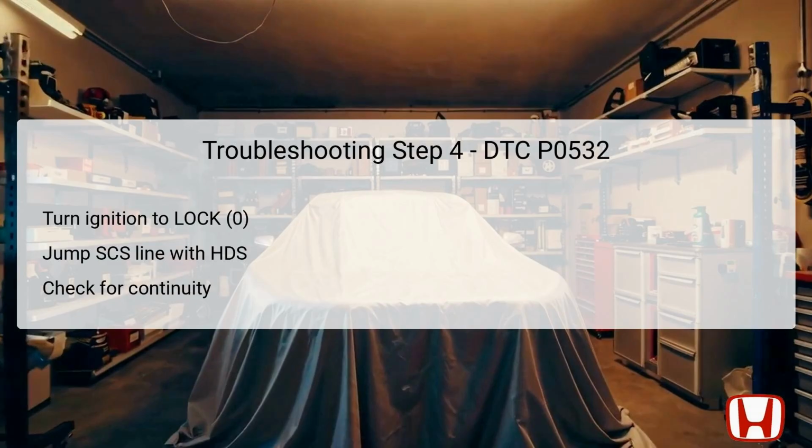Continuity testing is essential to determine if there is a break in the VCC6 wire, which connects the ECM to the AC pressure sensor. Check for continuity between 2 specific test points using the appropriate circuits. If continuity exists, this indicates that the VCC6 wire is functioning well, and any issues may lie with the ECM. If there is no continuity, repair any identified open circuit in the wiring to regain proper functionality.